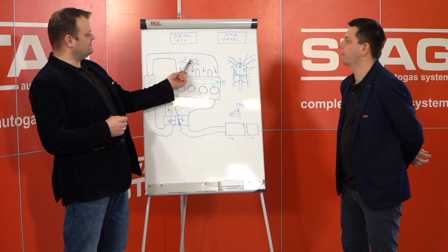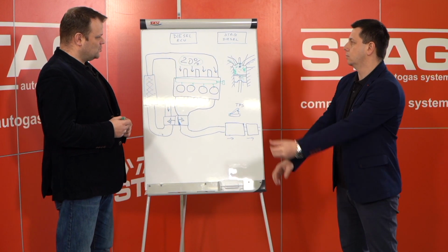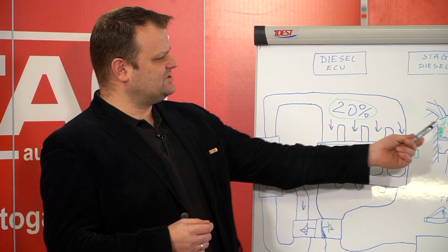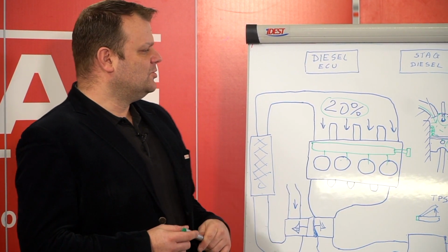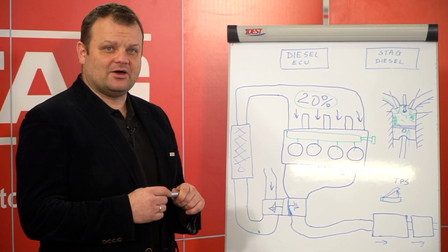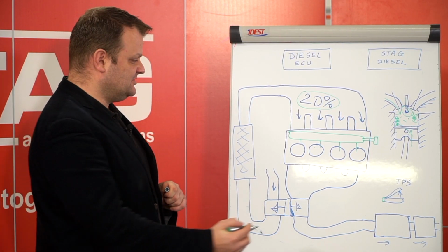And because we have, of course, the dosage of air in the inlet manifold, to control the proper mixture and the proper combustion process in the cylinder, we need to measure the output level of the oxygen. That's why we have a lambda system, and we need to mount this lambda system in the exhaust pipe.